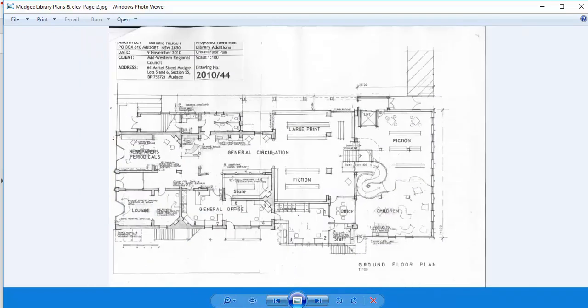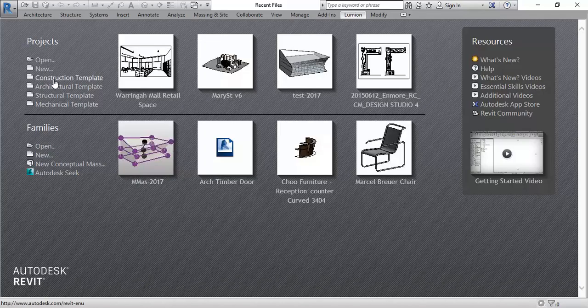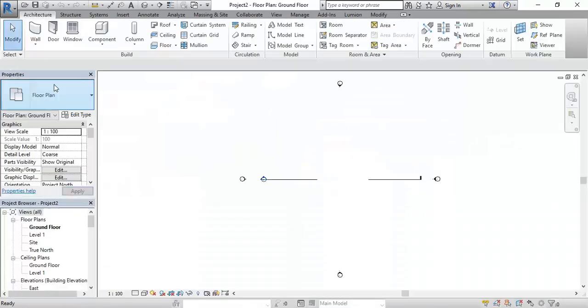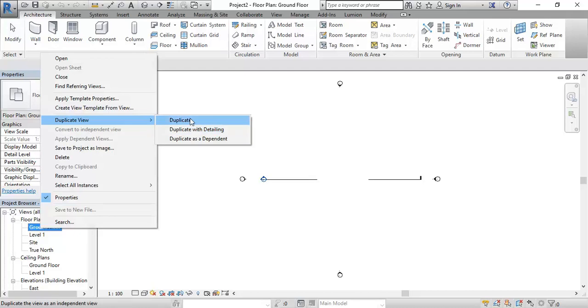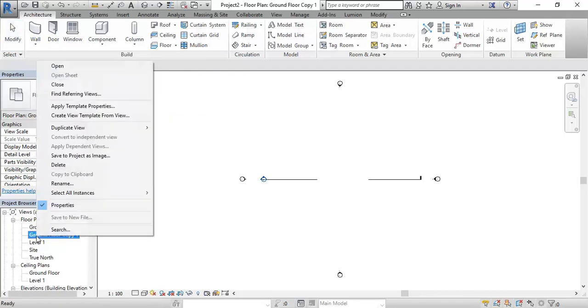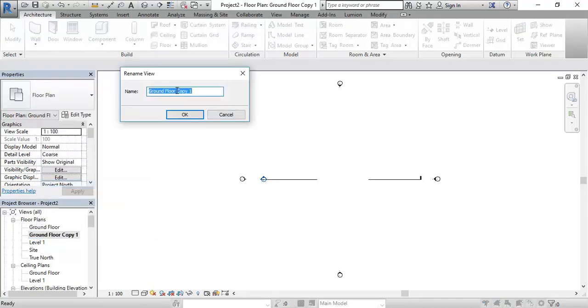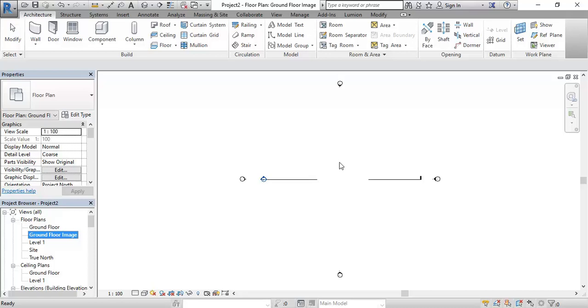So now in Revit, I'm going to make a new file using the architectural template, as usual. And then, as you're probably used to with me, I'm going to duplicate the ground floor view before I do anything else. Just by right-clicking there, I'm going to go to Duplicate View, and then Duplicate. Then I'll right-click on that new ground floor copy 1, and rename it and call it ground floor image. It's just for you to know, so you can really call that whatever you like, as long as it tells you that there's...